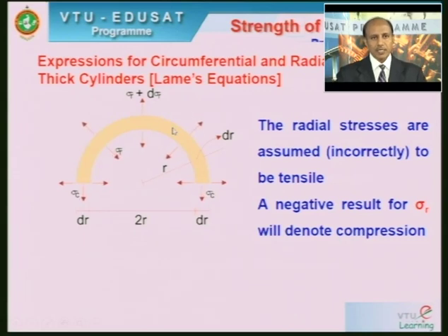So, the cylinder is subjected to two different values of radial stress, internal and external, and the thickness of the shell is dr. Now, at this cut surface, besides the radial stress, the circumferential stresses are also exposed. You can see at these two cut surfaces the circumferential stress sigma c and sigma c. So you have to carefully remember and write this particular free body diagram.